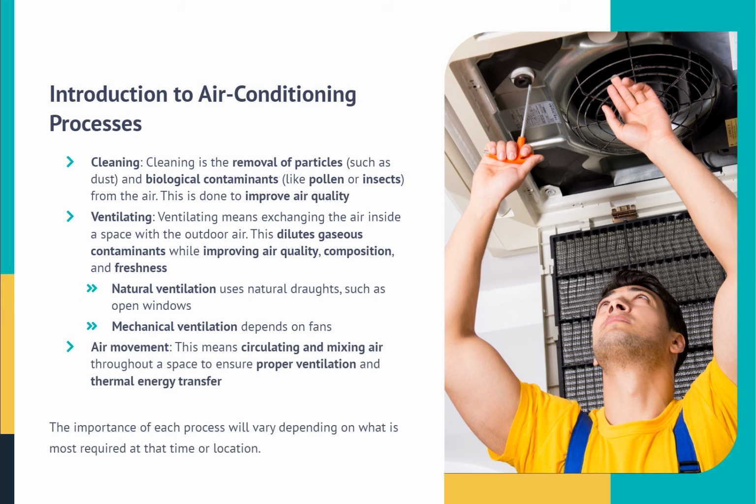Ventilating. Ventilating means exchanging the air inside a space with the outdoor air. This dilutes gaseous contaminants while improving air quality, composition, and freshness. Natural ventilation uses natural drafts, such as open windows. Mechanical ventilation depends on fans. Air movement. This means circulating and mixing air throughout a space to ensure proper ventilation and thermal energy transfer. The importance of each process will vary depending on what is most required at that time or location.